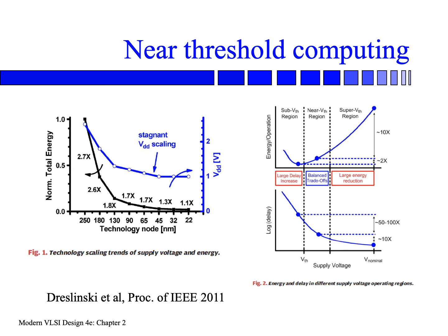So I think starting around 2010, there has been a huge research effort in the digital design community trying to push designs into so-called near threshold computing. Near threshold computing means that we reduce the supply voltage to a very low voltage, such that the voltage is even close to the threshold voltage region.